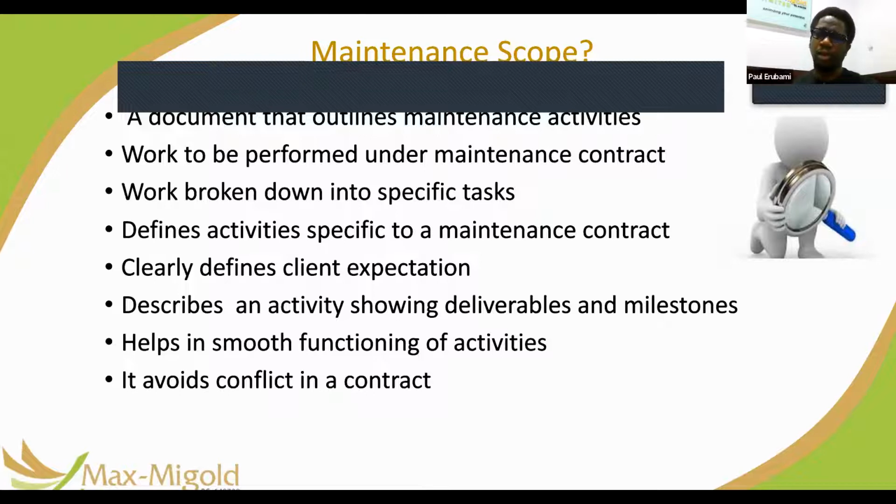Then they check the oil level. If the level is okay, then they use their hand to feel the oil viscosity. If it is too low, then they will take out the oil and put new oil. But if it feels a bit okay, what they would do is check if it is reduced in quantity. If it's reduced in quantity, they just do a little top up. And this was going on and on for months, running into a year.